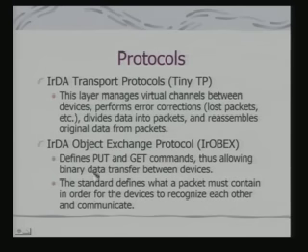On top of this, you have the object exchange protocol. These have the kind of transactions which are defined over here. It defines put and get commands, thus allowing binary data transfer between the devices. So, the actual data transfer which takes place between the devices goes through put and get. In fact, when you are doing this transfer on a PC, whether this data is to be accepted, received or sent, that gets translated effectively into these put and get commands.